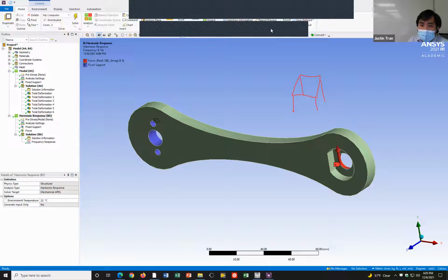Ideally, you would want to apply the oscillatory force here, because that's where the earthquake is going to be hitting the ground. The difficulty with this is that you also need to use the bottoms of these posts as fixed supports, because that's where it's fixed to the ground. And so if you apply a force there, that force actually won't transmit to the rest of your structure because that's also a fixed support.